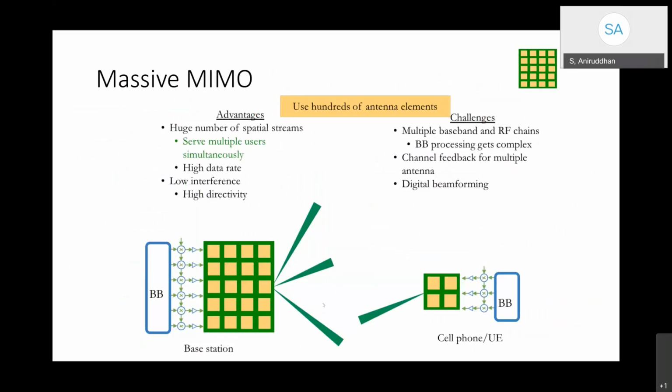adding additional complexity to the hardware, because remember now in massive MIMO you are going to have 1024 RF chains. So the minute you need to do hybrid beamforming, you need to add additional analog circuitry 1024 times. So the idea of not choosing that is to keep the complexity of the RF to a manageable extent.